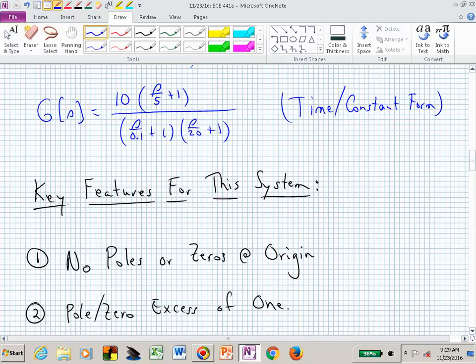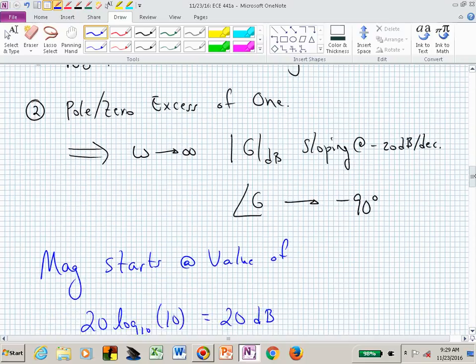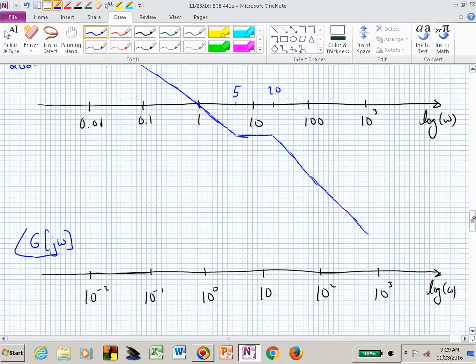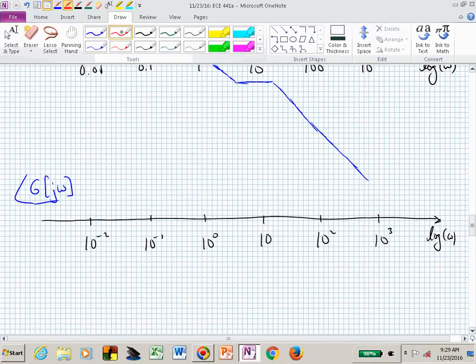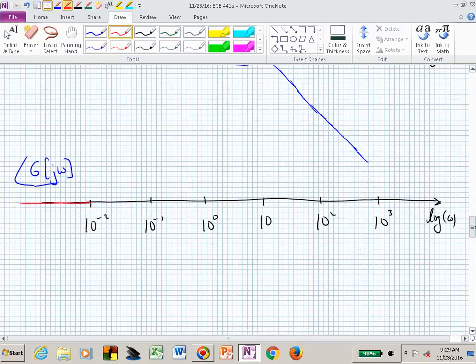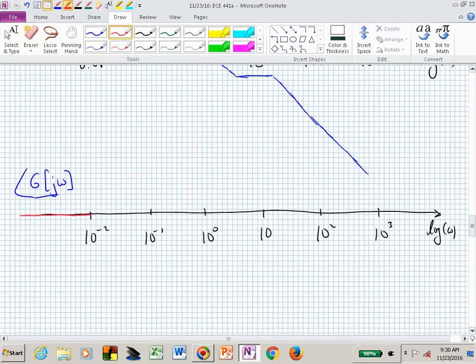In this case, we need to start the slope of that first pole a decade before 0.1, or 0.01, and we start going in which direction? So in this case, we were here until 0.01, and then what happens? Actually, it gets a little bit challenging maybe to add and subtract or to keep track of all these bends and breaks on the phase. Sometimes it's not that easy to start at the left and just draw it to the right. So let's look at each individual piece.